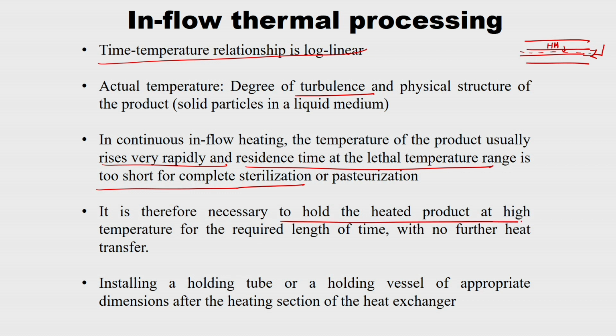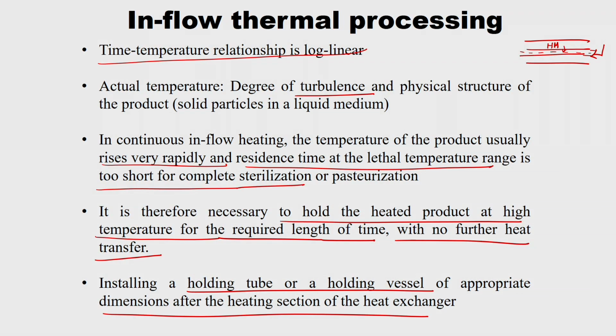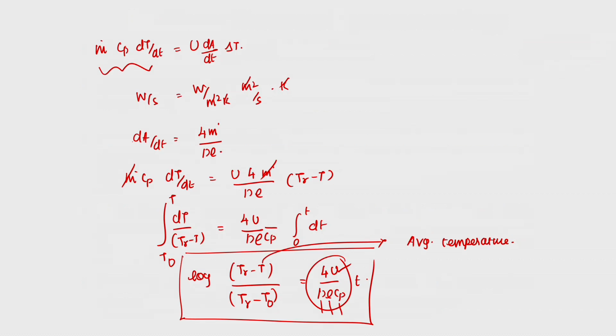It is therefore necessary to hold the heated product at high temperature for the required length of time with no further heat transfer. No heat transfer will happen; the holding tube will hold the particular food product at that particular temperature. Right. So, that is nothing but a holding tube, holding vessel. So, this is designed in inflow thermal processing. After the heat exchanger there will be a holding section, where the food product is maintained at constant temperature, but held for some time, in the sense the required time to get the particular lethality during sterilization or pasteurization.